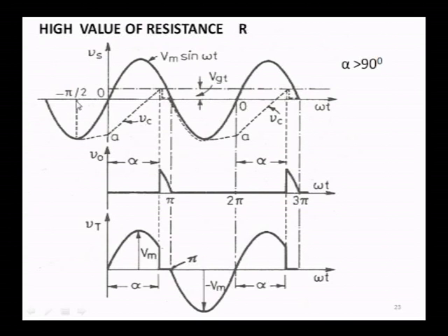So, a similar thing happens here, once again during the negative cycles of the input, the capacitor charges to the peak value. So, when the input crosses this 0 or reaches 0, the capacitor voltage slightly reduces, and when the input voltage goes in the positive direction, your capacitor starts discharging. So, this is the discharge path, it has taken a long path, and until it reaches VGT, your SCR will never fire.